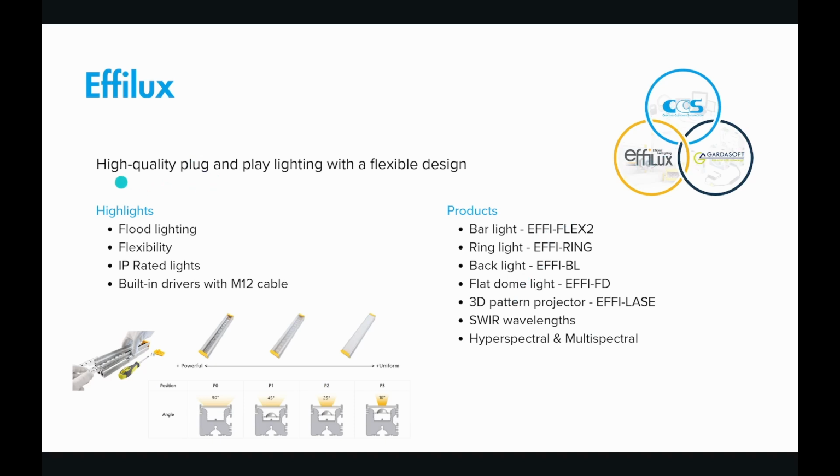For FE-Lux, the purpose of these lights is that they are high quality plug and play lighting. They have M12 connections, so they can connect directly to a smart camera. They have built-in drivers where they will auto strobe, so they'll be overdriving for the first initial few hundred microseconds or 2 milliseconds, and then go down to continuous use. They also have the ability to open up the light and you can adjust the lens to change the emitting angle, or you can adjust the window to optimize your uniformity versus your intensity.